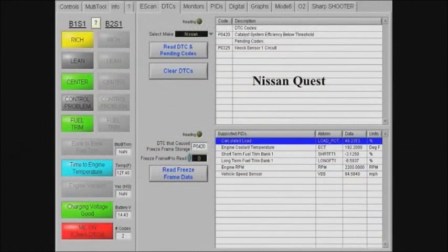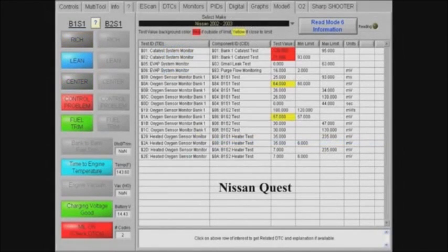A Nissan, the difference with this 420 is I have a knock sensor code. Very common on Nissans, right? Well, some guys like to cut the wires, clear the code out and go, I hope nothing happens. Well, the newer cars, you can't do the wire cutting trick anymore because the light will be on. You need to fix the problem. And if there's a knock sensor problem, remember the top 10? Number 10 was timing. Does the knock sensor have anything to do with timing? Is that going to do something to that cat? You bet. So there's the information, and fuel trim is not too crazy, a -8, nothing nutty on long term.